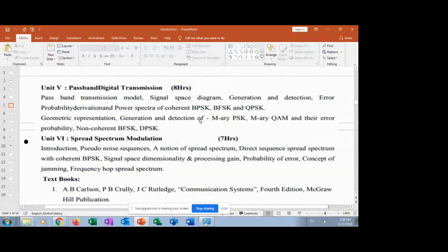Because, as we know, the simple definition of modulation is that some part of the carrier signal changes according to the baseband signal. Now we have the baseband signal in digital format, 1 and 0. Let us consider if we have the information 101, which is 3 bits. Here we can see 1 to 0 and 0 to 1, that is the shifting. Whenever there is a shifting, the parameters of the carrier signal change.